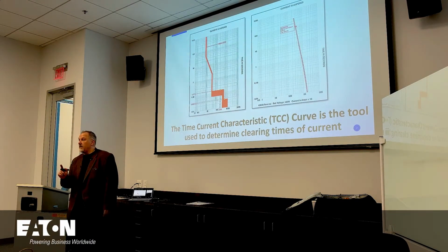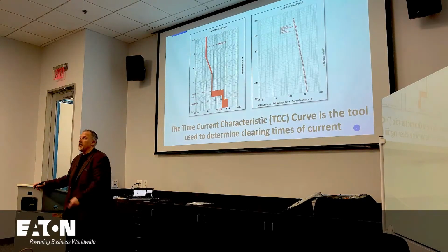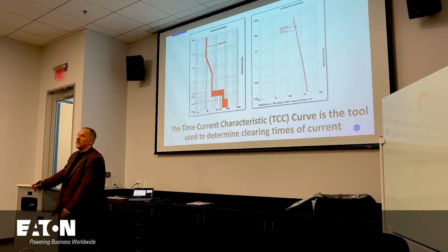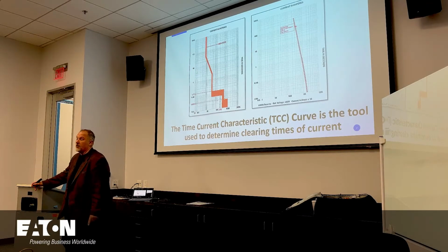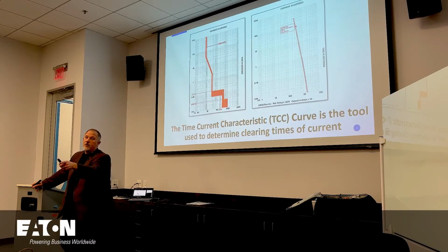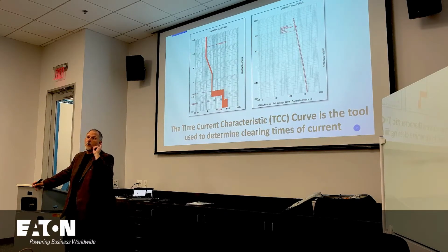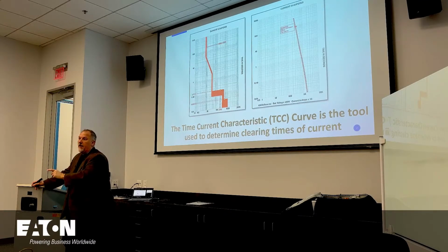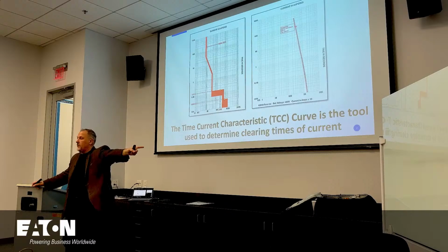Right. So I could accidentally, now what do we do in the code to reduce the likelihood of that for service entrance equipment only right now for 2020 code? I put barriers to Article 230. And we put barriers in the 2017 code in Article 408 for panel boards and switchgear. And we added panel boards in the line side barrier requirements for service entrance equipment. And we moved it to Article 230 and we said any service entrance equipment, we want barriers, but you can't rely on the barriers for calculating incident energy. You always have to go to the supplying overcurrent protective device.